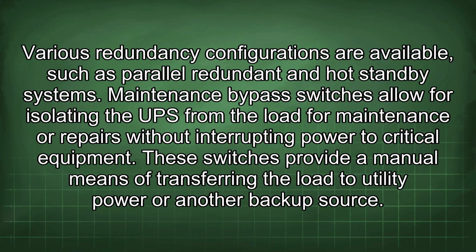Maintenance bypass switches allow for isolating the UPS from the load for maintenance or repairs without interrupting power to critical equipment. These switches provide a manual means of transferring the load to utility power or another backup source.